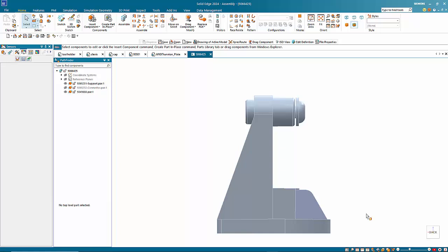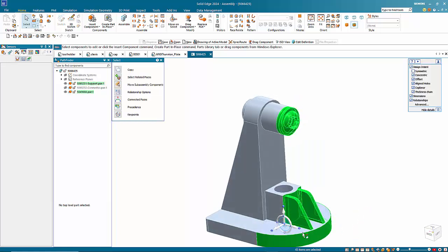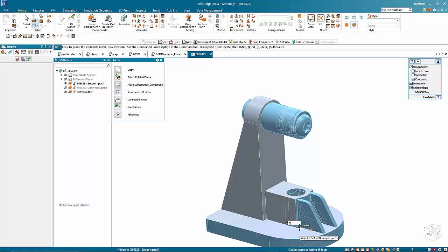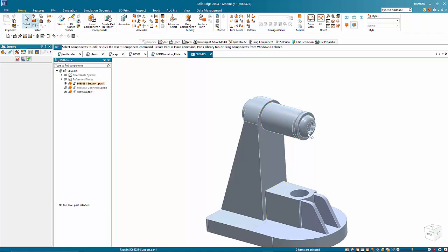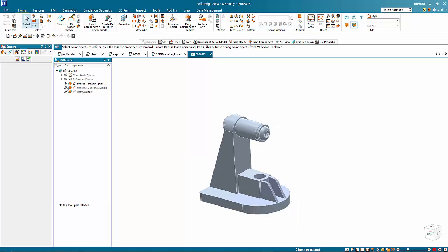Just look at the side view, and if I go Control Shift, see the cursor's gone to a whitish color, so I can do a fence select on faces in the assembly now, and I can increase the size of this by say 5 mil, and that's modified both this part and this part. Let's go back to base, and because we applied our relationships, the mates on here have still held together.